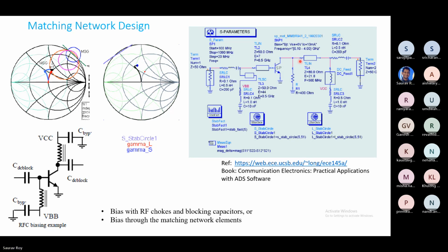Okay. So now how can you add a inductance? The easiest way is you can use a lumped inductor, or might be a better way is to use a high impedance line. As you know, if you remember for our filter design, we represented inductor with a high impedance line of some particular length.